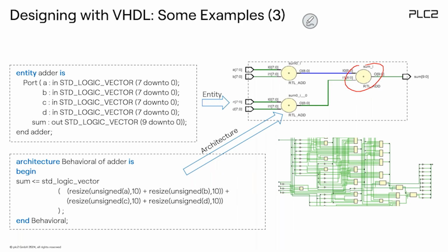So in this case, we would have to write it something like this. It's A plus B, but now use parentheses, plus, again use parentheses, C plus D. So in this case, the VHDL compiler will do in parallel A plus B and C plus D, and then implement this one.